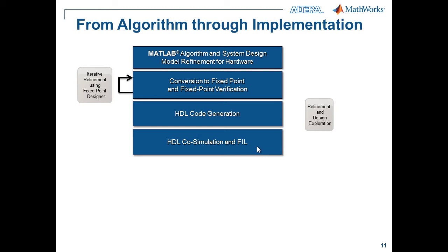There's FPGA-in-the-loop, where we will take the MATLAB test bench and run this against the actual bit stream or the hardware implementation that is put on our Altera FPGA evaluation board. There's also a standalone co-verification phase where we would take fixed point stimulus and reference results that are generated during the fixed point verification phase and actually run those as a standalone HDL verification. That we would also do during this phase here.